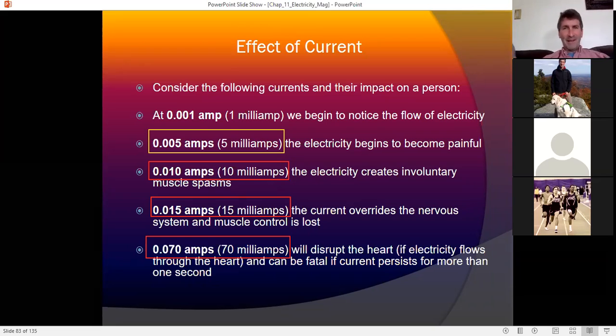Whenever I'm around electricity, first of all, I take my little voltmeter there to make sure that everything's dead. I make sure all the circuit breakers are turned off. But even then, I will only touch it with one arm or one hand. I'll keep my other hand in my pocket, because if I grab on to something that's electrically charged with both hands, the electricity will go in one hand, go through the heart muscle, and go out the other hand. So very, very important.